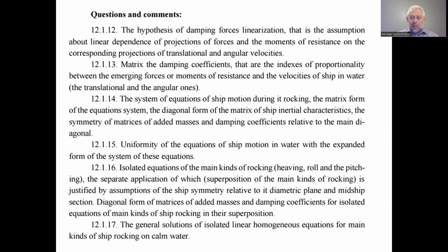And the way of use is exactly different. So we use the added masses for the ship acceleration characteristics, sorry, elements, and the damping coefficient matrix we use for the ship velocities in all directions, not the accelerations.